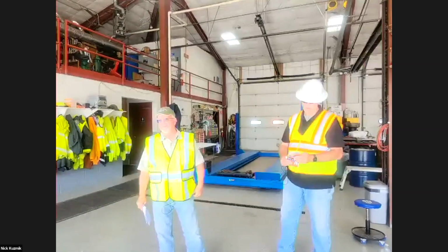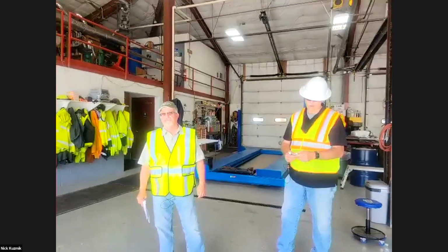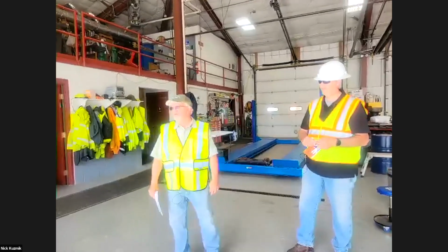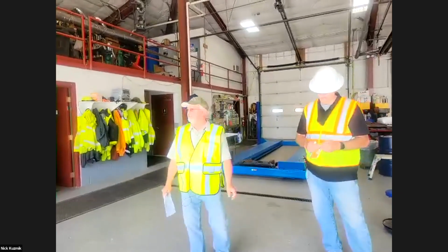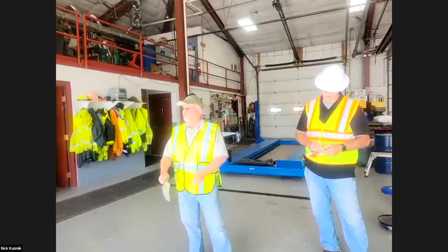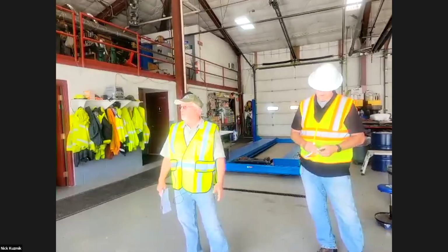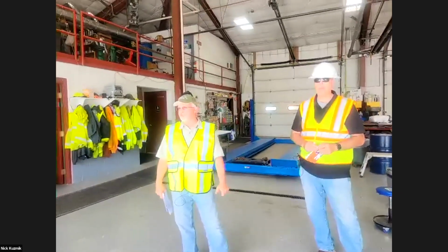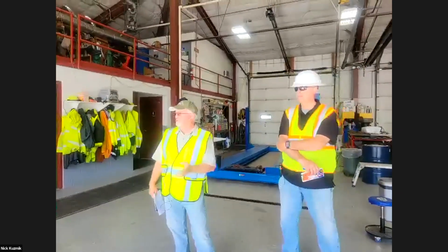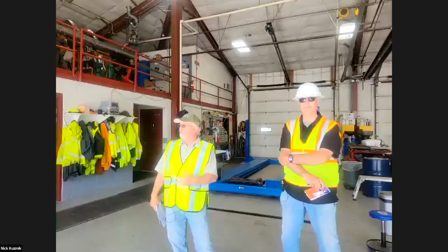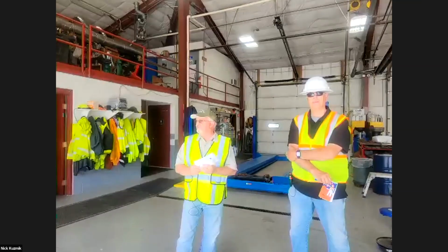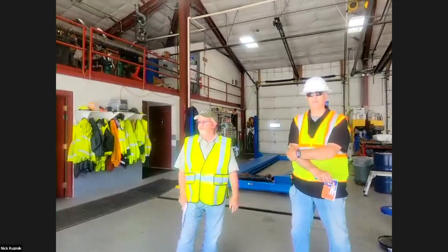So what's the most important rule while flagging in a work zone? Pay attention. Stay alert, pay attention. Don't drift off, don't use your phone. Again, your job is to protect the workers. You need to stay alert. You've got to protect yourself too. Give yourself a way out in case traffic isn't stopping. But you also want to be there to alert the workers to prevent them from getting injured in any capacity. Everybody wants to go home, as Joel had said earlier.